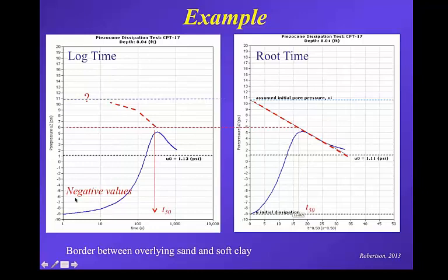So you always have to question with these complex shaped curves, especially coming from negative and rising up, about whether or not it's truly got to equilibrium yet. Now the question here is, of course, negative pore pressures in a dense till, and so I'm assuming it started negative and never went positive.